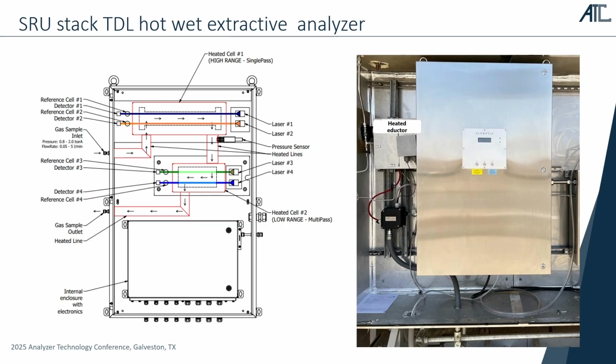The whole enclosure was IP66, and as I mentioned, we were able to provide ambient temperature from -20 to +60 degrees C, which was a requirement for the Middle East. We deployed it 3 years ago in one of the refineries in the Middle East, and we passed all these validation tests. The analyzer was working basically without any issues, even during the upset conditions, when SO2 went up to 1 volume percent.